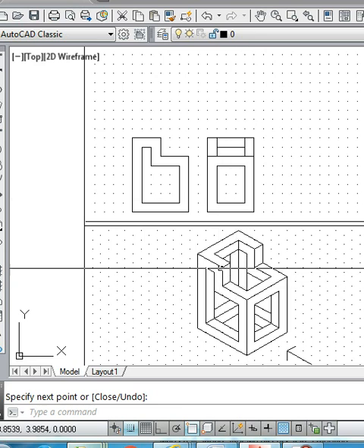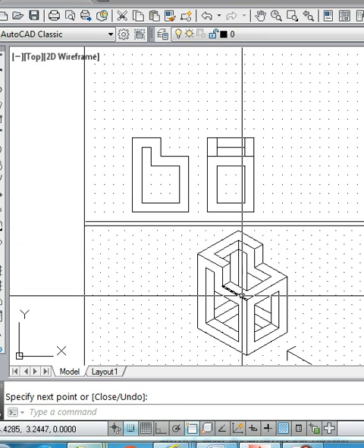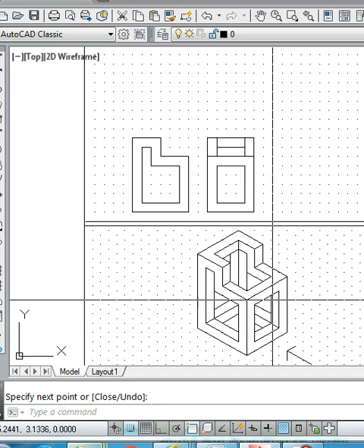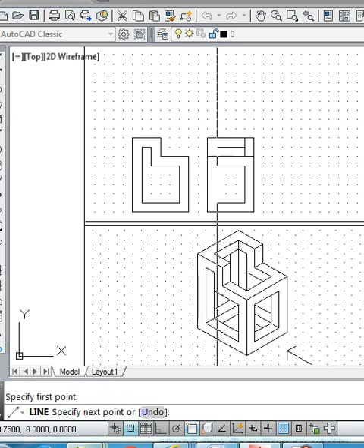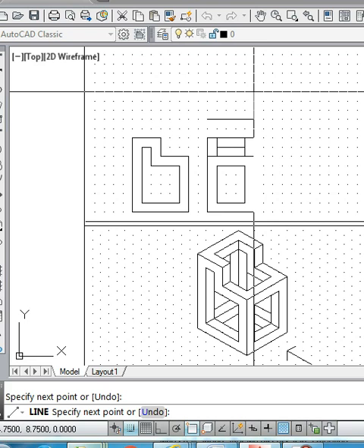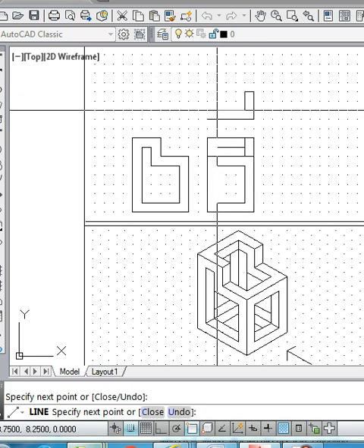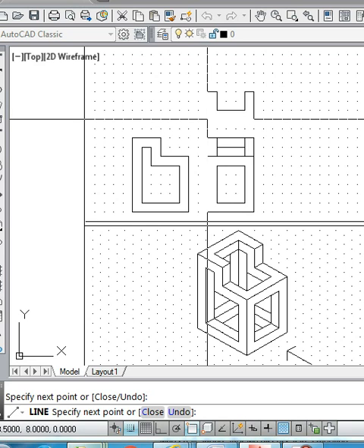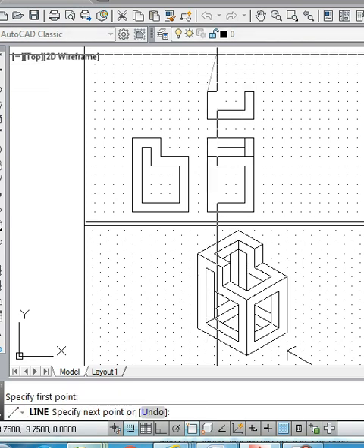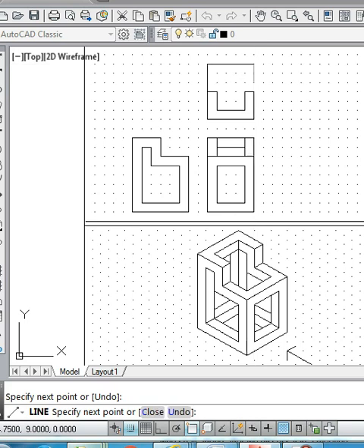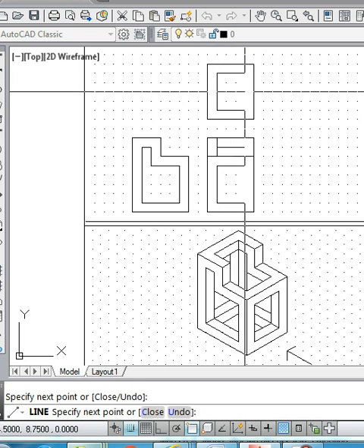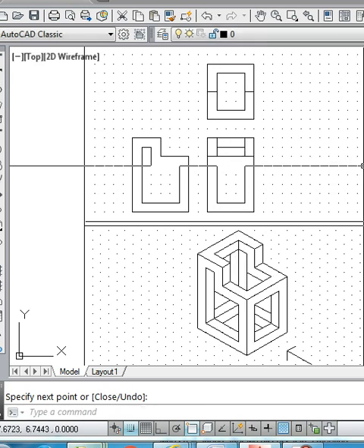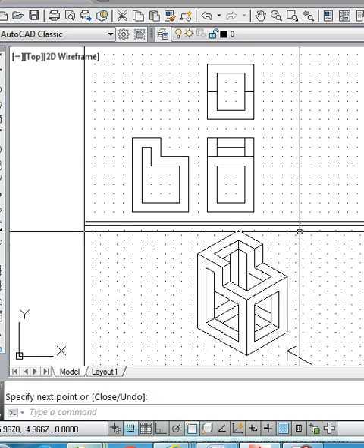Now from the top, you see there is one C here, and you have another C here. The top view has to be drawn above the front view and in complete alignment. So we complete it here. This C, 3 grid spaces will be its depth. This is one C. You have another C, again with 3 grid spaces. Another C. That is how it will appear from the top, but it is all neglecting the hidden edges, without which the drawing is incomplete.